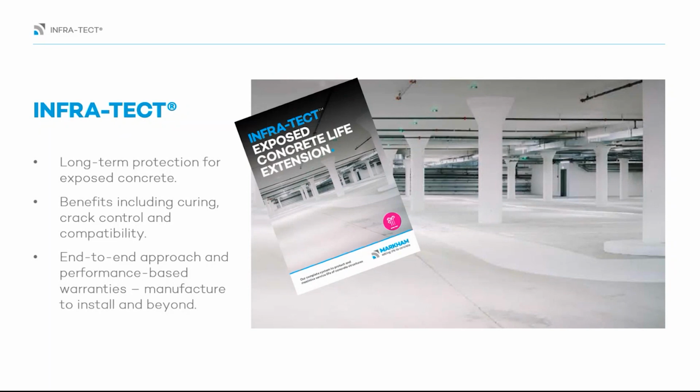Working in with the designers to ensure that systems like these are specified early or documented so that we know that it's going to meet a performance requirement for a project. Benefits of that is good curing, crack control, compatibility, as you mentioned before, Wade. So the fact that we're not putting anything foreign into the concrete still allows the natural finished concrete to remain compatible with any topical products such as line marking, etc., in a car parking situation.